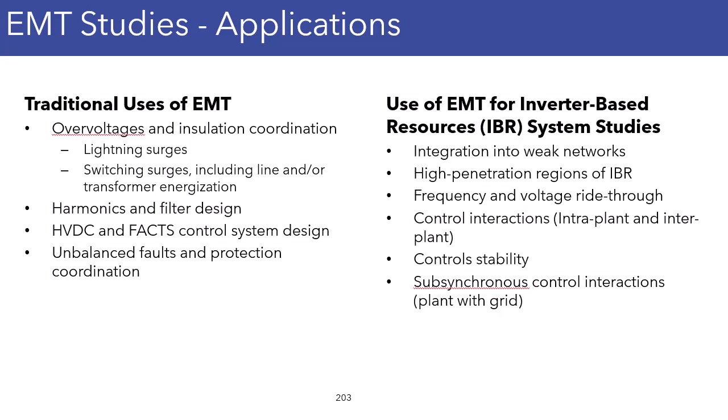High penetration regions of inverter-based resources. Think California, some parts of Texas, some parts of Minnesota. So places where frequency and voltage ride-through are required. And now that frequency and voltage ride-throughs are being required, EMT is good for studying those.